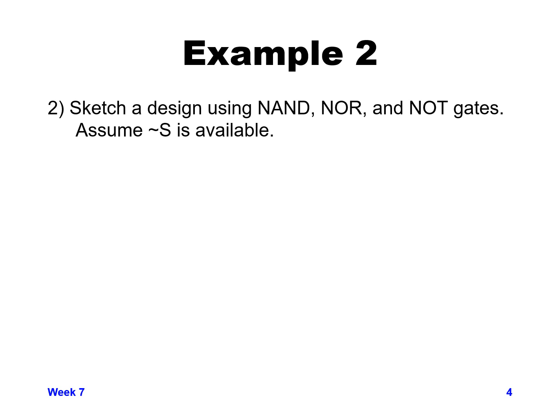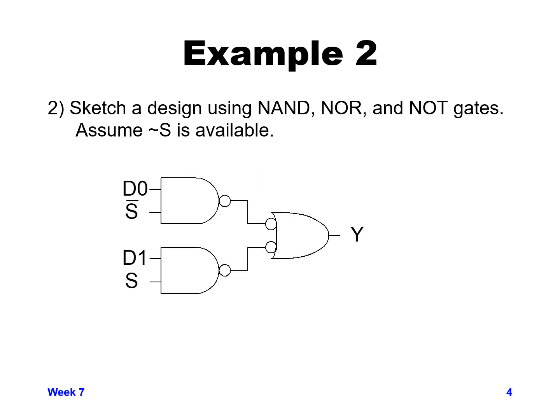So now that you've tried it yourself, we'll go through what we could actually design here. It looks very similar to the previous design where we had two AND gates followed by an OR gate, but since we're using NAND gates, we have an AND NOT at each of the AND gates, and since we want to follow that by an OR function, we can do a NOT OR.